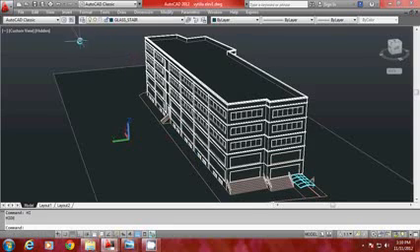You can see that you have one vanishing point over here, because when you draw lines along these edges, you can have a vanishing point here, and when you draw lines along these edges, you will have a vanishing point on the right side, and these lines are no longer vertical, they are inclined. So when you produce these edges and when you draw lines, you can find a third vanishing point underneath. So this is a typical example for a 3-point perspective, and this is how you make a 3-point perspective.